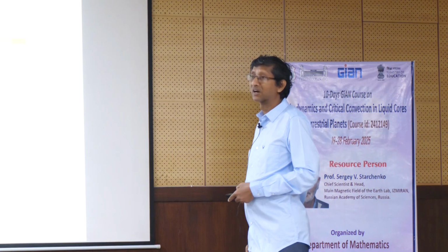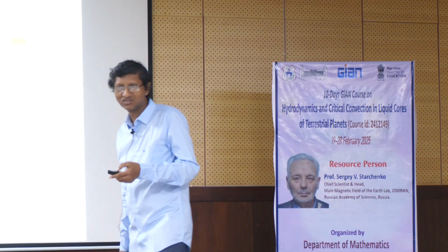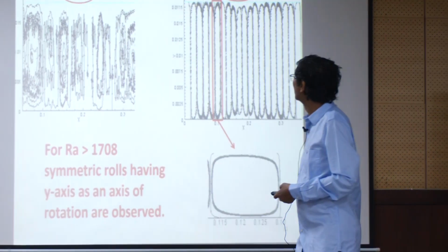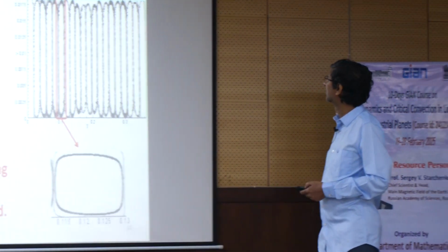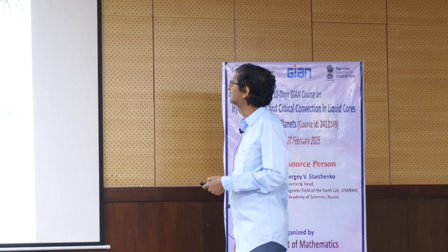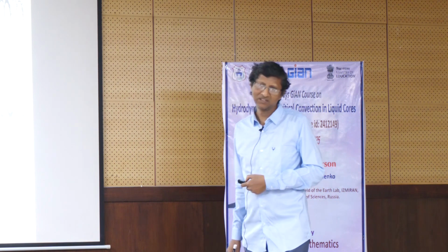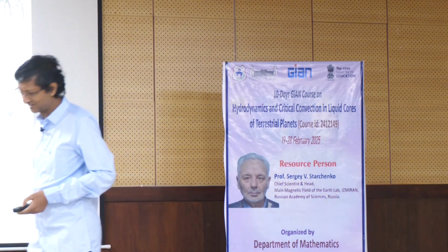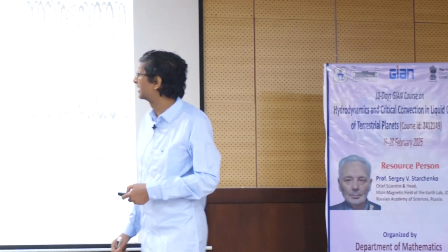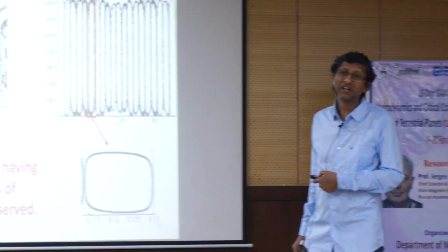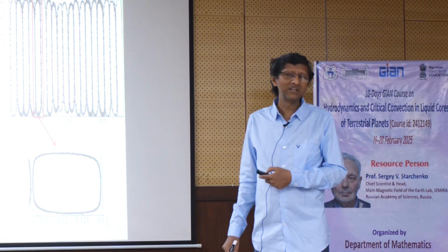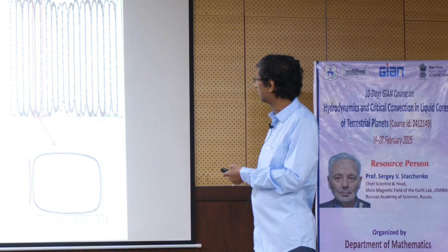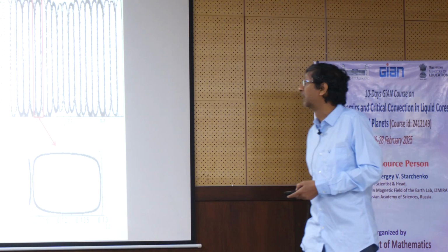Of course, Professor Rani published a paper in Geophysical and Astrophysical Fluid Dynamics. She was able to trace out, taking the Rayleigh numbers like this one, these patterns, but these are not regular patterns, right? So what is the value of the critical Rayleigh number when the boundaries are rigid? 1707, but here it is not 1707. The number is 800. So we can say that the flow is there, but it is a subcritical flow. Okay, so these are all done using some DNS methods, and she was able to get it.